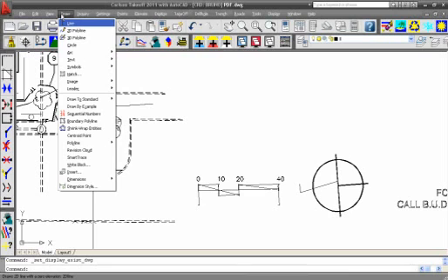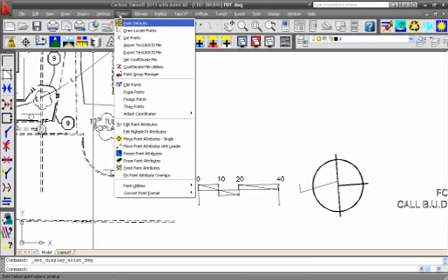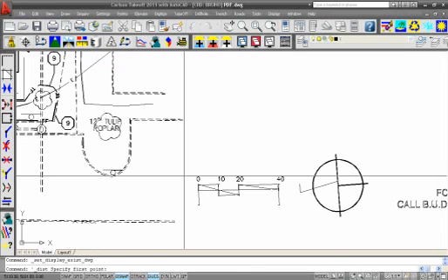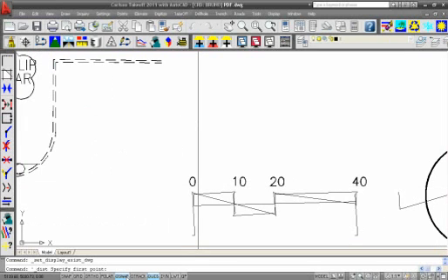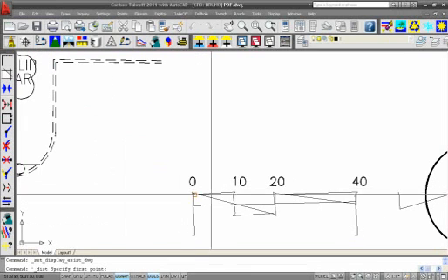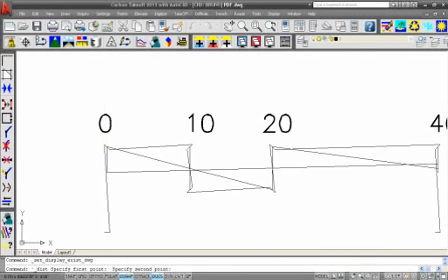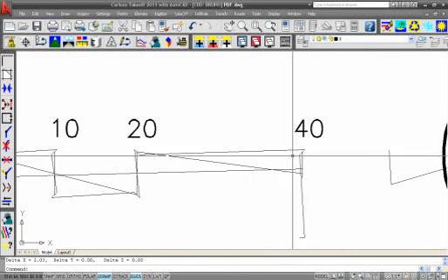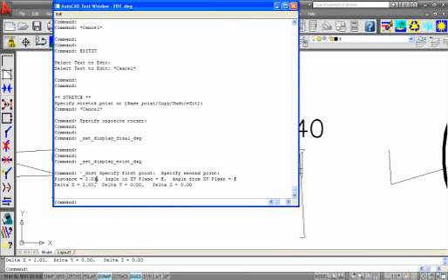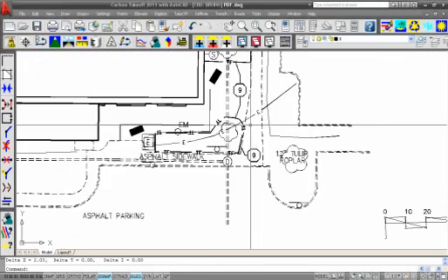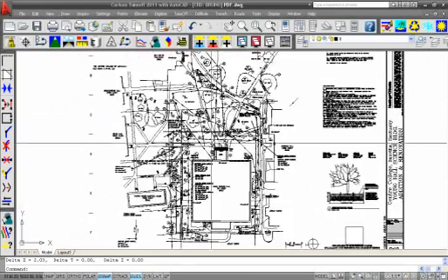Importing a PDF, your drawing is not going to be scaled accurately. If I do an inquiry, standard distance, and let's turn my O-snap on. From 0 to 40, this should be 40 feet in the drawing. If I click here to here and F2, that distance is a little more than 2 feet. So obviously the scale is wrong in here. All my volumes would be way off.